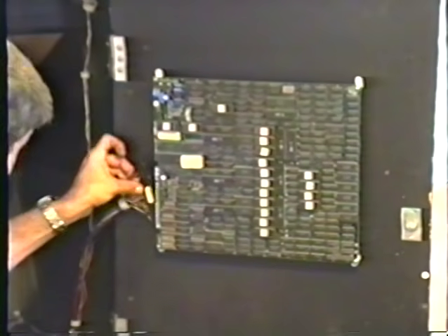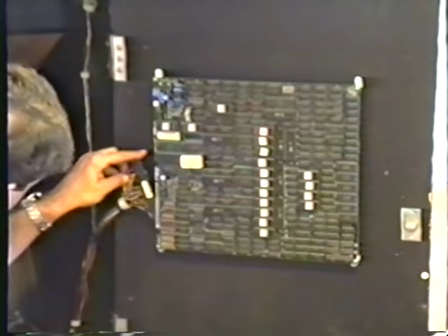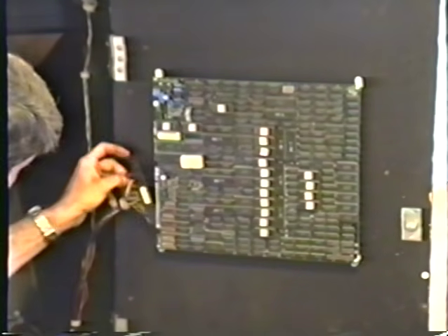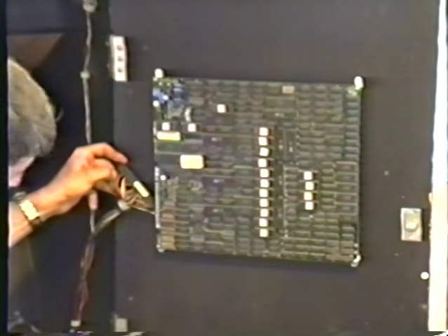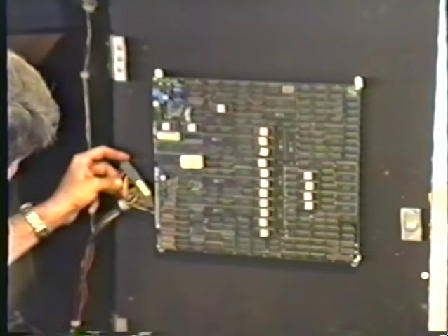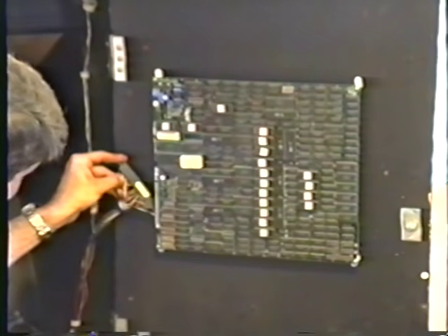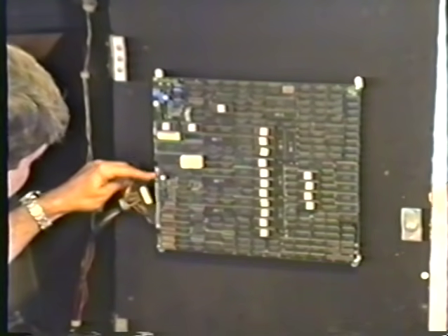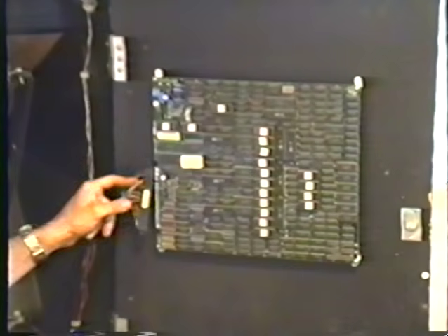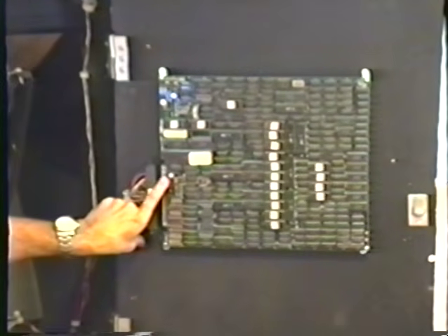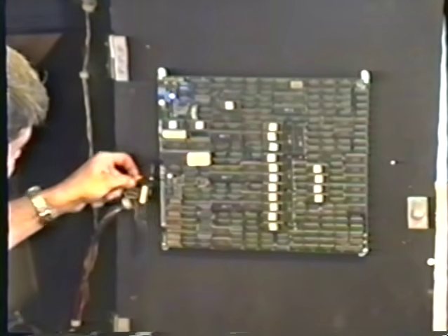You may find that the minus 5 volts is unused in some games. It apparently is not used in this game because I have the ground wires, they're black. I have the red wires, that's for the plus 5. Then there's a blank spot right here. Pins 5 and E are not used, so this game doesn't use the minus 5. If you have a standard connector with minus 5 hooked up, and the board doesn't use it, that's okay. It's just not hooked up to anything. On the board here, there's a little pin, but it's just not used. And then the yellow wires for the plus 12.